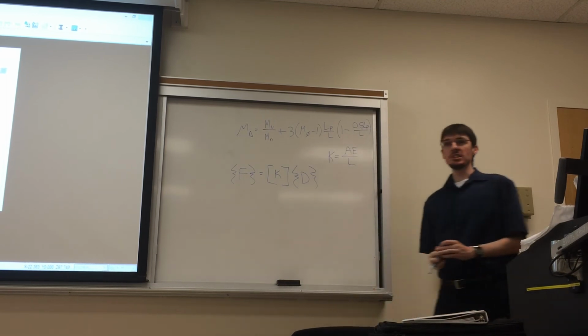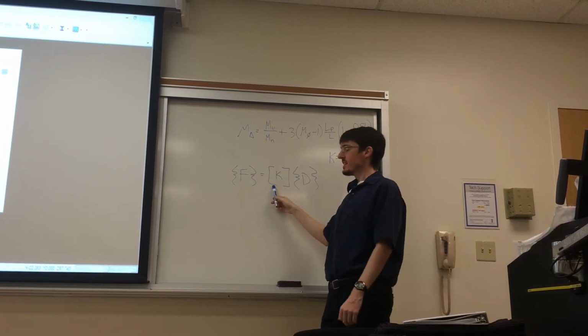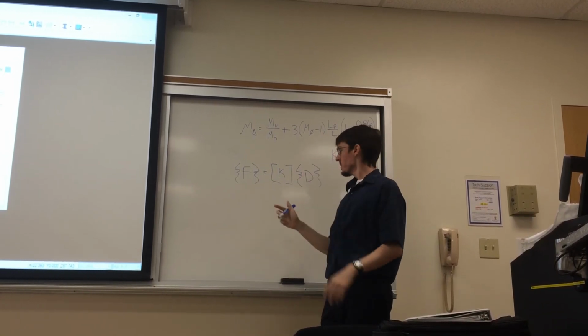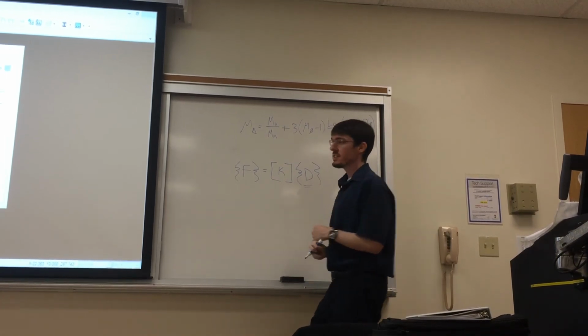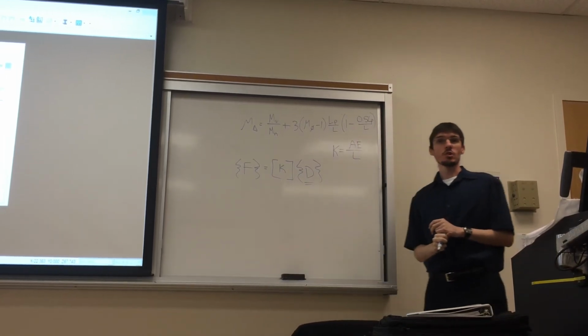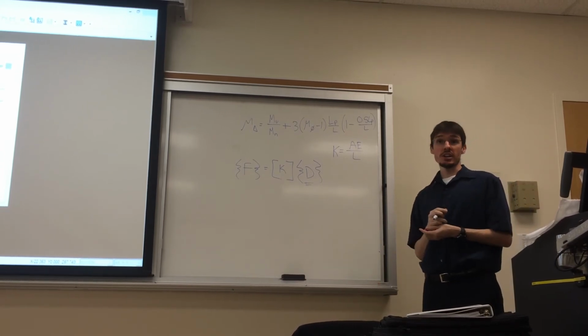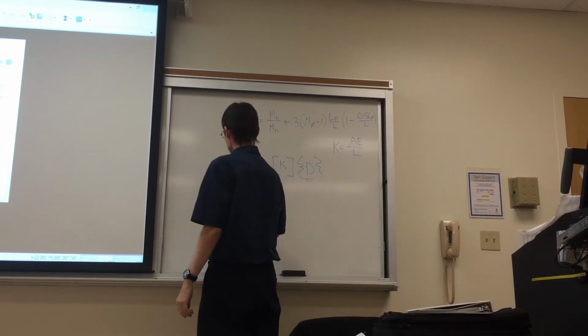For a multi-degree of freedom system, your forces that develop in your frame are equal to a stiffness matrix, which is relating the stiffness of each member and each node together, and displacements. And I said that this is a displacement-based method, so it's solving for displacements. Generally, you're interested in, let's say, forces and moments and such, though. So how does it get those? It inverts the stiffness matrix.